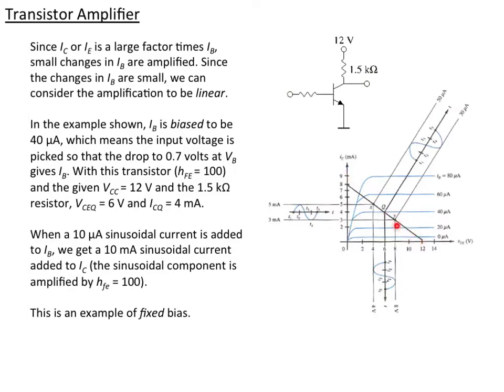That's given by the load line here. And so if we draw more current, we go to a higher line, the current coming through goes up and the voltage goes down. Likewise, if we drop the current here, this voltage goes up, and we go to a higher value here.